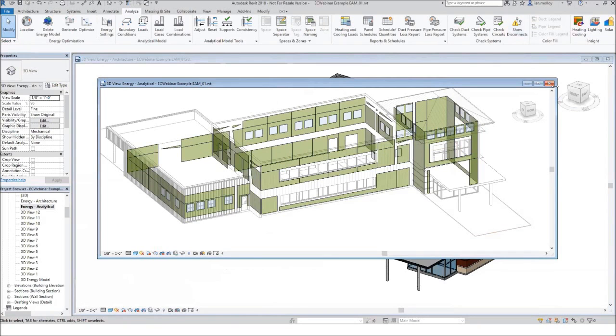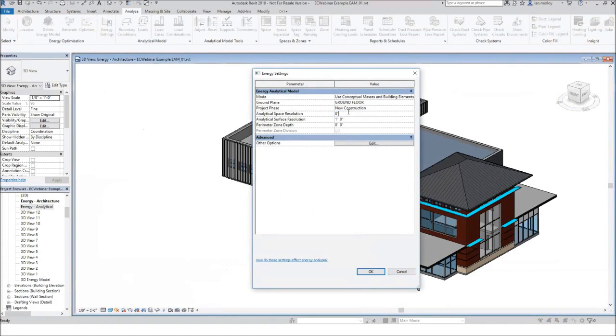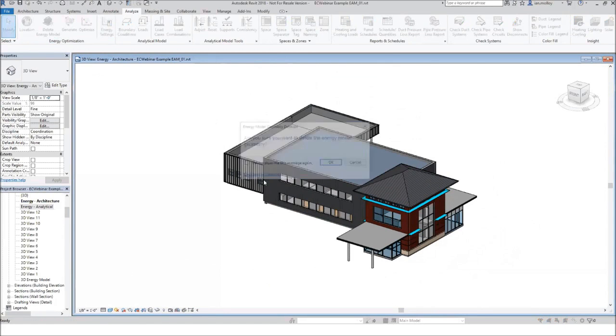So what I'm going to do is increase the resolution. All right. So if I go in here, I'm going to just jump down to 8 and 4. This is essentially the same effect as doubling the volume. If you halve the resolution, it's like doubling the volume. So this can take 8 times longer, which again is another reason why it's good to remove any elements that don't play a role.